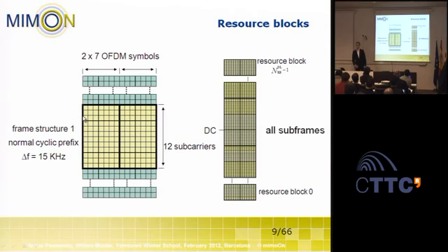One resource block is the smallest quantity in LTE on which scheduling decisions are made. So basically this is the smallest time-frequency resource that can be allocated to a particular user. In this system we have the subcarriers placed 15 kilohertz apart, and these are denoted as resource elements.